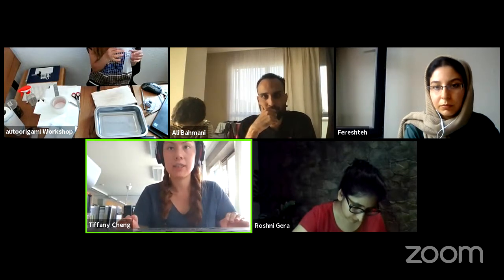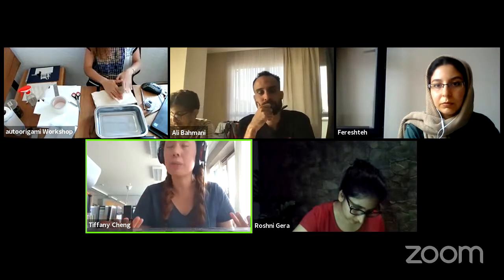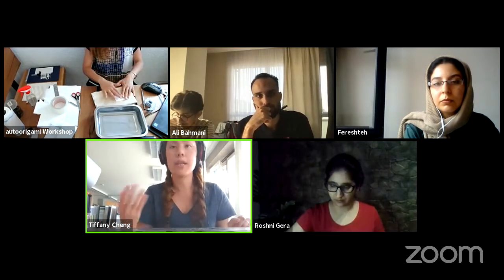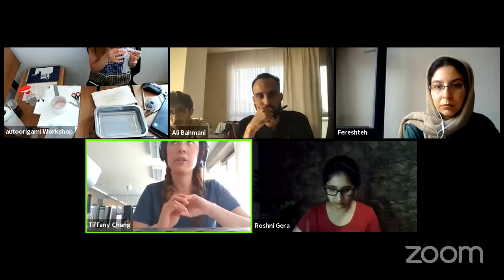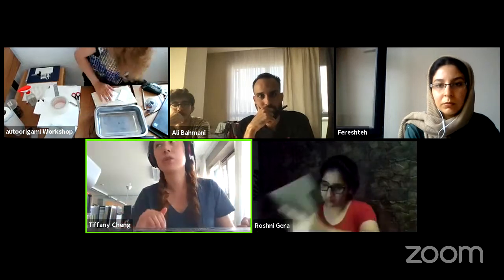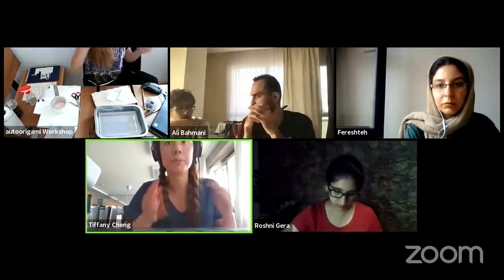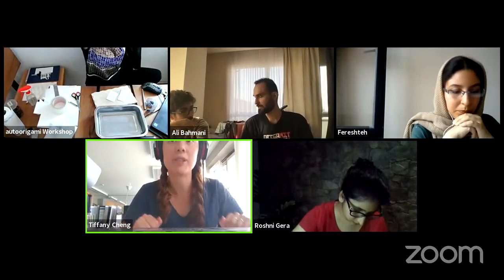The conditions in which we manufacture it flat are what the shape is going to be when it's dry, and when it's wet, it is going to curve. So if we reverse this programming by manufacturing the bilayers when they're wet, then the flat configuration is going to be when it's at high humidity or wet, and when it's dry, it's going to curve. So we're flipping the programming, where it curves when dry rather than being flat when dry.